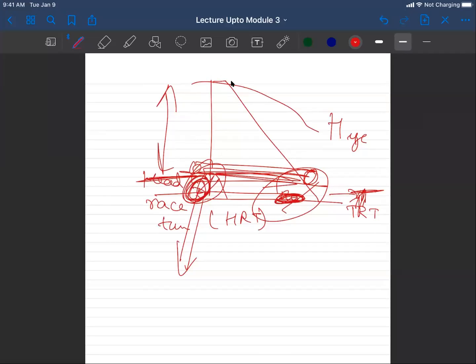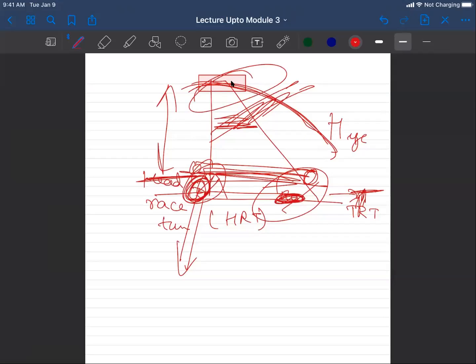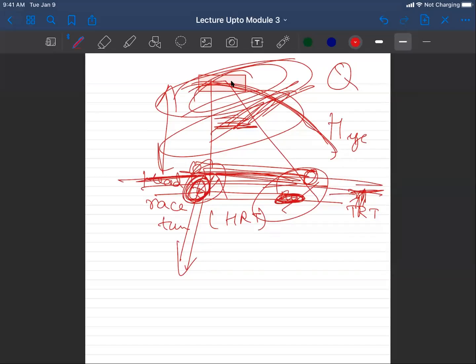Okay, so when they say they've released a certain amount of water, they mean the spillovers. Yes, and also there are double provisions for spillover. You would have these top gates, of course, and in some dams there is a central gate also, around the centroid, because sometimes it may happen there is a cloudburst upstream, and these gates may not be sufficient to release enough water. Ultimately, it's the discharge. It's not the volume; it's the rate at which you are discharging the water. So when they say all gates are open, that means these gates are open, these gates are open, and there is a short circuiting that they have done between head race and tail race.